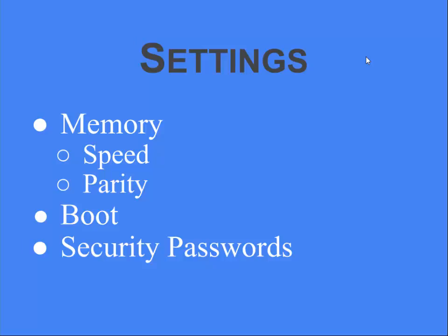It's this, not this. Parity, P-A-R-I-T-Y. What even parity means is you count up the number of switches that are on. We're using even parity, so we say, okay, there are 5 bits that are turned on. Is that even or odd? It's not even, so you put a 0 here.